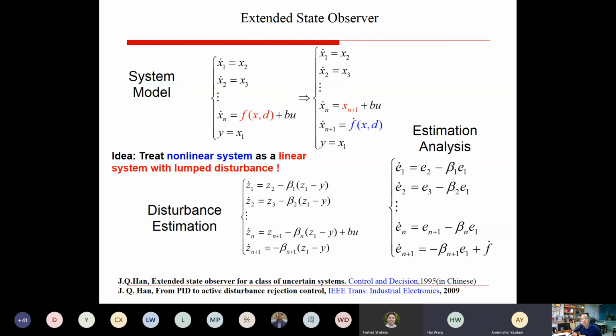I think there is maybe some misunderstanding in this data. For the 80 or 85%, usually we call it PID, but it's for the engineer controller. They don't have a very rigorous consideration of PID. For the motion control people, we know you always use friction compensation to reject or cancel the friction.